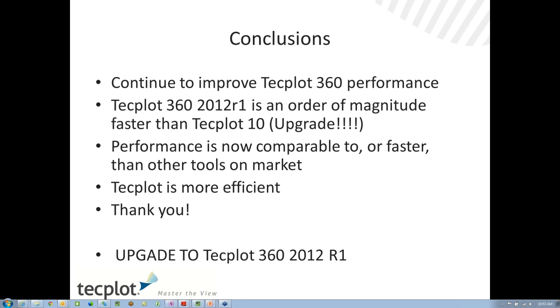One person had asked about when you're doing rotation, does it recalculate stream traces? Because we had a pretty nice refresh rate. If you're doing surface stream traces, there's this offset default that sometimes people have on, which sometimes will look like the stream traces or the contour levels are jumping off the geometry. It's just a setting, and we can show you offline how to do that, but that's usually an artifact.